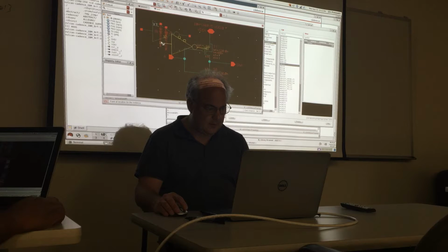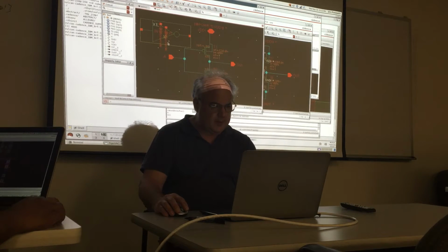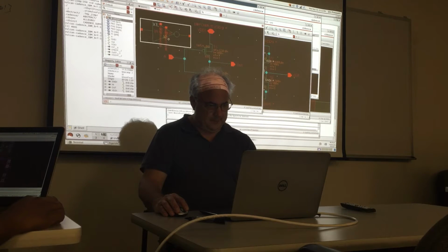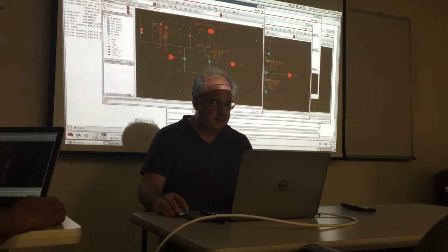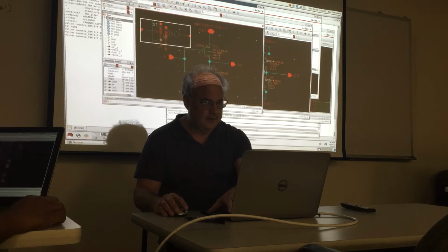I forgot to move the. Oh, this is another glitch. You're like, where's my VDD and ground connections? Okay, so you guys see how you create the instance? It's just like you do any other instance. You create instance, and then you can choose the library, and it'll bring the symbol in. And since I have the origin set right there, when I brought it in, the cursor was sitting right there, which makes it nice whenever you're positioning it.